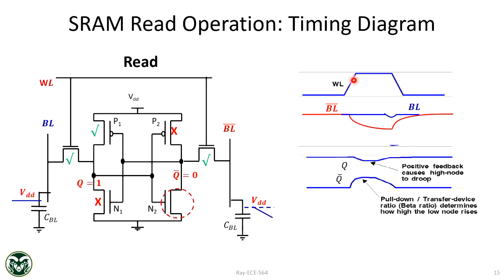And then you turn on the word line. The moment you turn on the word line, one of the bit lines will discharge. And a few millivolts is good enough, because there is a sense amplifier connected at the end, which will amplify the state.